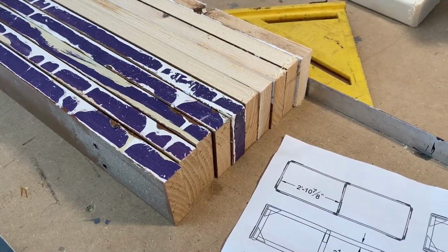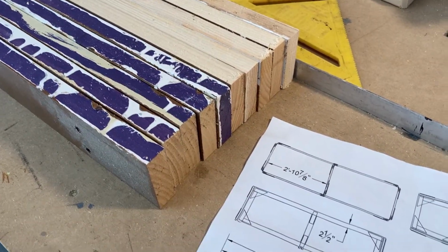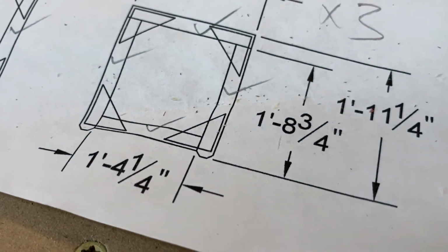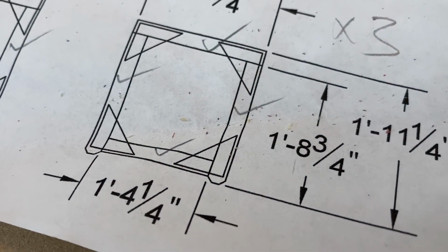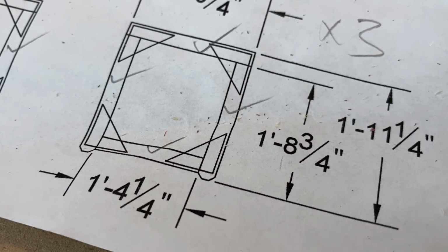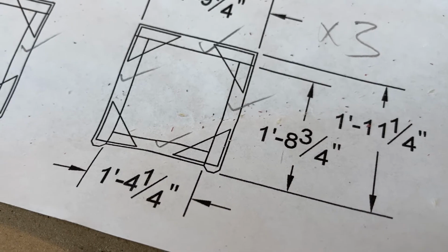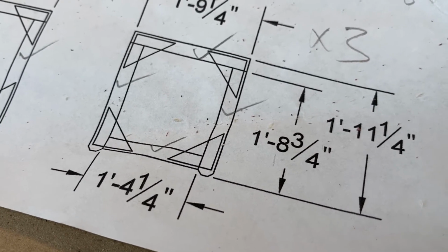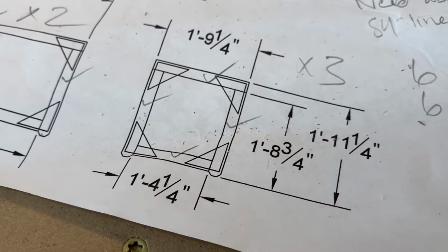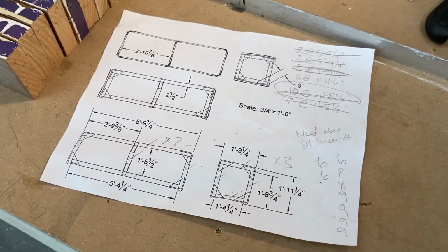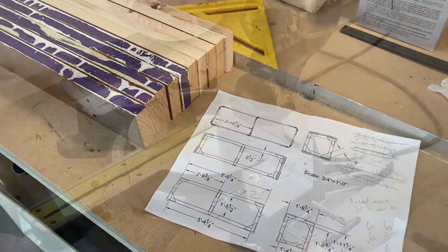My stack of 10 pieces at 1 foot 8 3/4 are destined to become the sort of outer piece of the frame that also serves as a leg where it makes contact with the floor. So you might notice at the very bottom there, I'm actually going to nip off the corners at a 45-degree angle, leaving a much smaller surface area to contact the floor. This really just helps make it easier to shim when you're putting it on a stage that may be unlevel, and it also looks kind of nice.